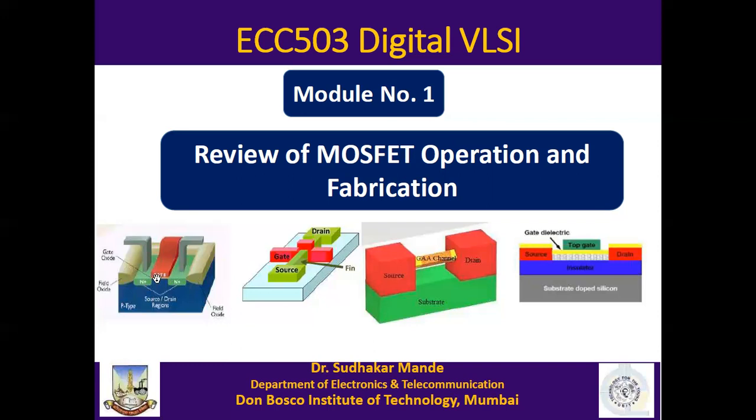Here there is only one gate and control is only from the top. But if you see, this is called FinFET, which is a novel architecture. This is a very thin fin and the gate is from both the sides. Therefore, control of the current is better as compared to MOSFET. But again, there are limitations of FinFET. That's why, can't we have a gate all around the channel? That is called a GAA channel MOSFET.